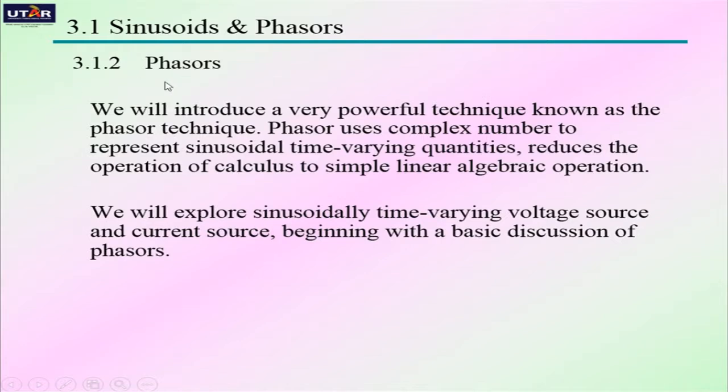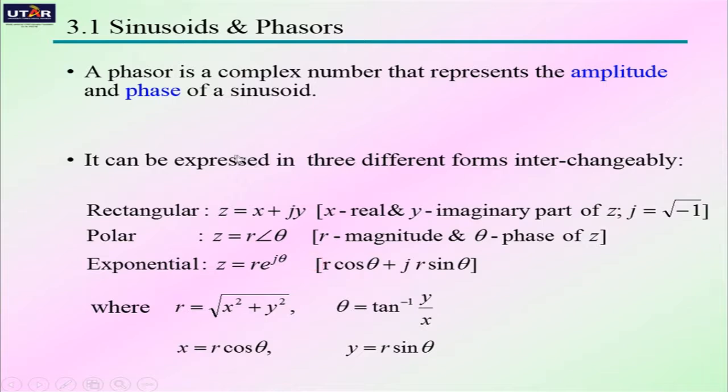So phasors, what are phasors? Phasors is actually the frequency domain representation of the voltage or current. Phasors use complex numbers to represent sinusoidal time varying quantities, and reduce the operation of calculus to simple linear algebraic operations. So let's have a look at what a phasor is here in detail.